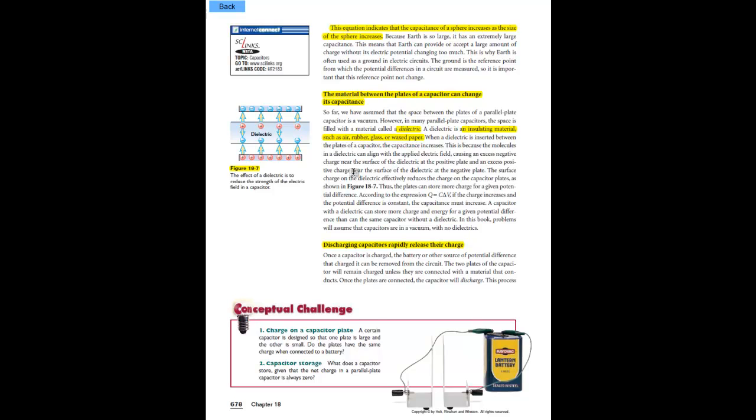Well, that kind of makes sense if we think about what's going on. During charging, charges from one plate, which was the positive plate right here, moved on to the negative plate. Originally, I had effectively no excess charge over here. So as electrons began to flow over, there was plenty of space for them to move around. There wasn't a high density of charges, and therefore the forces of repulsion were pretty low. But as more and more charges built up, that force of repulsion built. It became harder and harder to shove more charges on, and therefore charge motion slowed down.